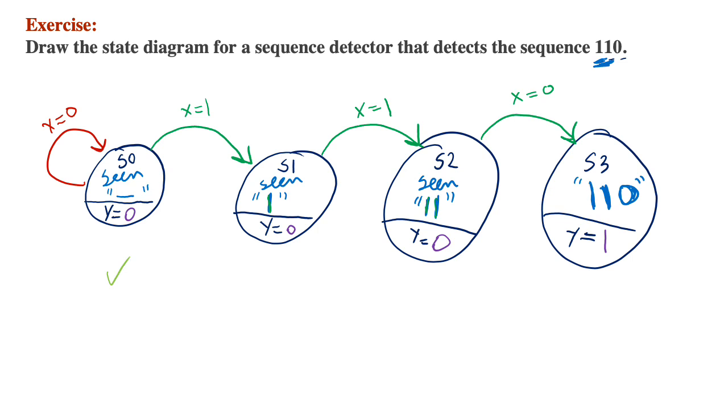Now the next step is to go to state 1 and take care of the case where the input is equal to 0. I know if I'm in state 1 and the input is 1, I'm going to move to state 2. Now if the input is 0 while I'm in state 1, what I'm going to do first is copy this 1 as it is, and then right next to it the possible input, which is 0, that I'm considering right now. Then I'm going to check if there is any state that says 1 0.